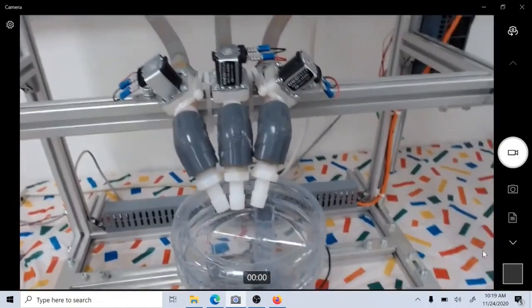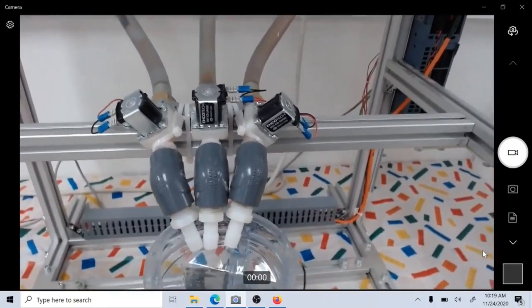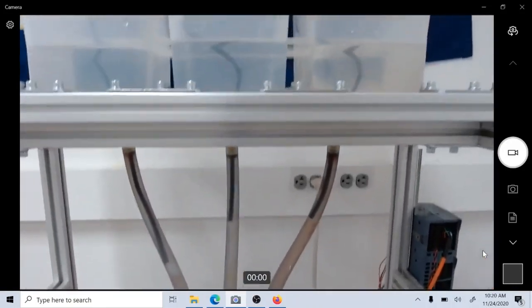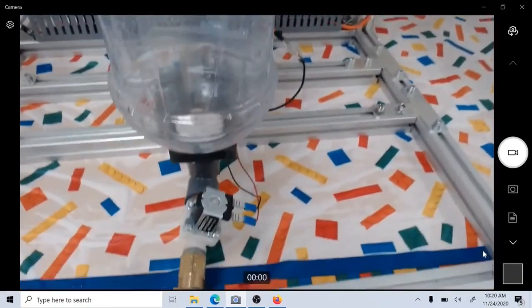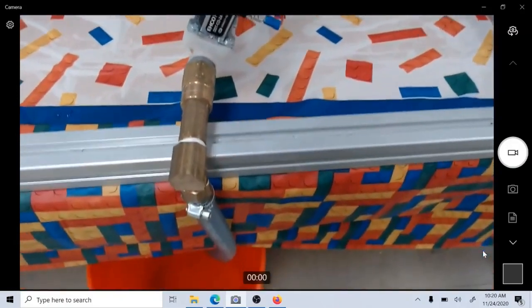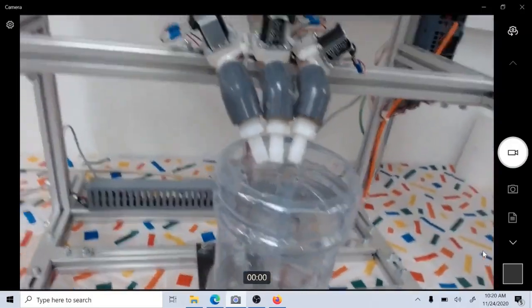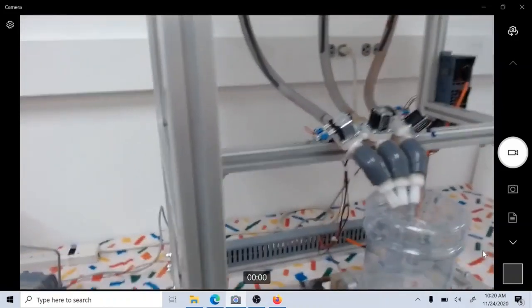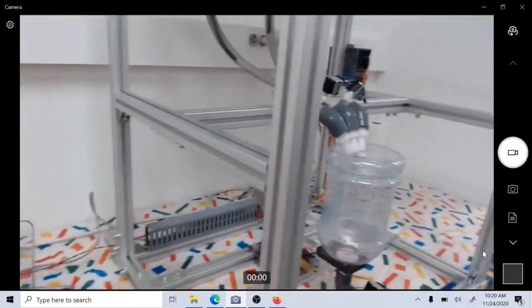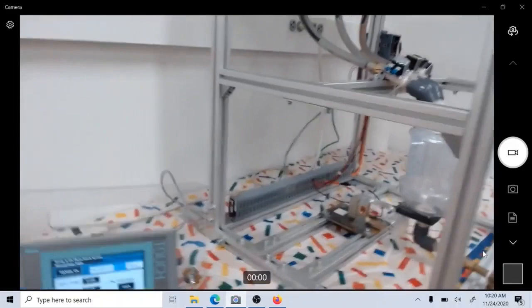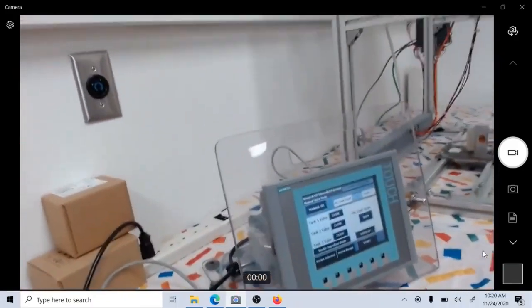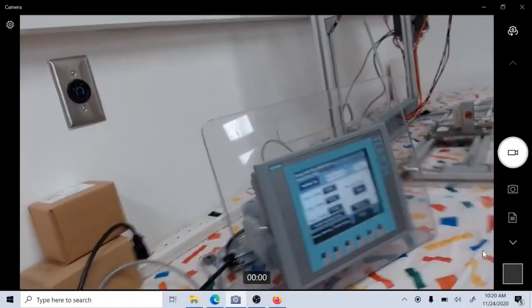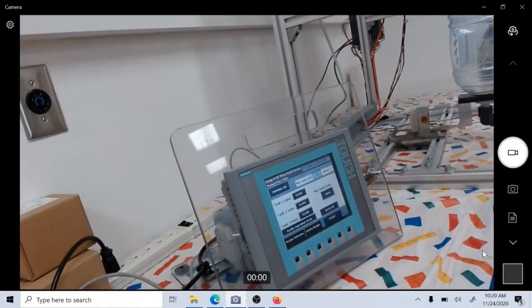You can see it, and then we go up here. There are 3 water valves that control the flow of water from these tanks up here, and then we have a flow valve that controls the drain that goes down to the bucket underneath. So we're looking at a process here where we mix some various ingredients together, and we're going to look at the process of doing this, we're going to look at the program, and the HMI part of it.